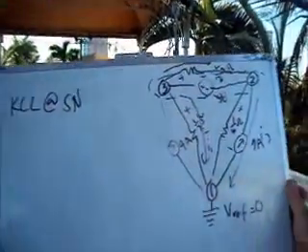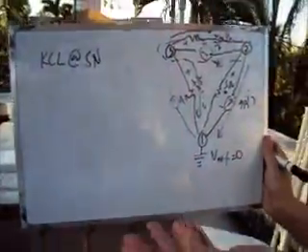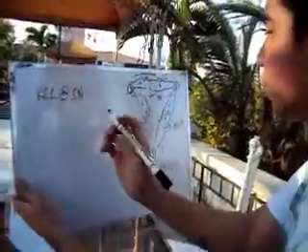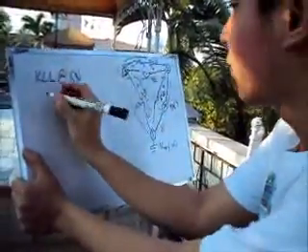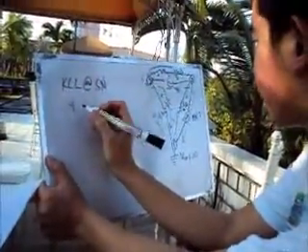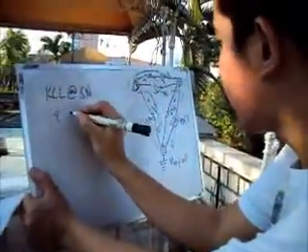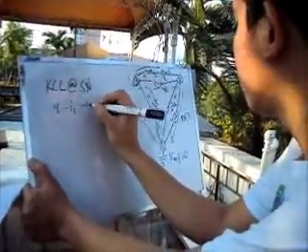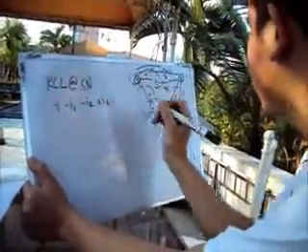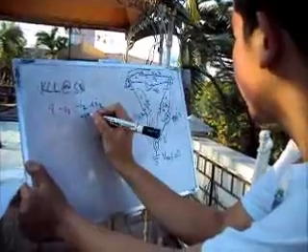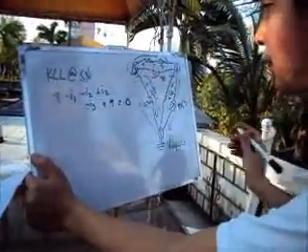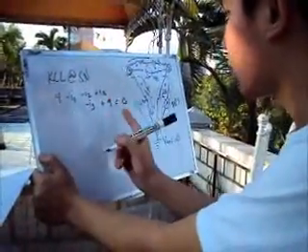This is our supernode. In Kirchhoff's current law, that law states that those currents entering the node are positive, and those leaving the node are negative. So 4 is entering node 3, the supernode, leaving I1, leaving I2, entering I2, leaving I3, and entering 9 volts, equals to 0. That is our equation 1.